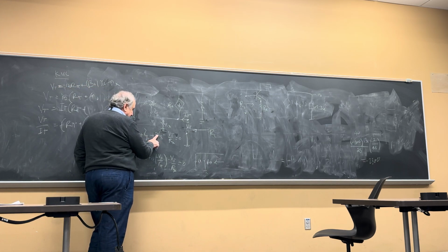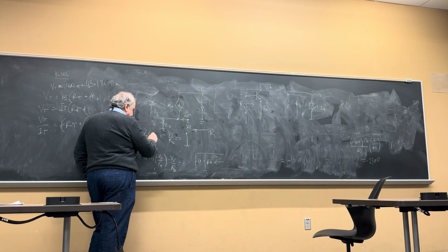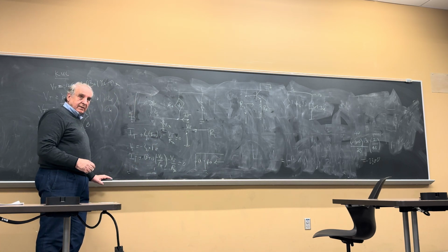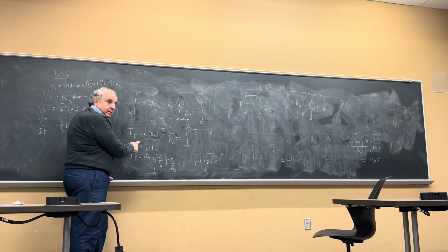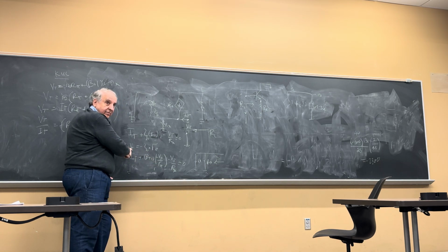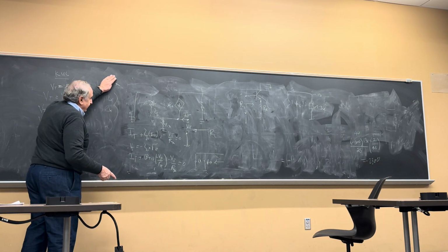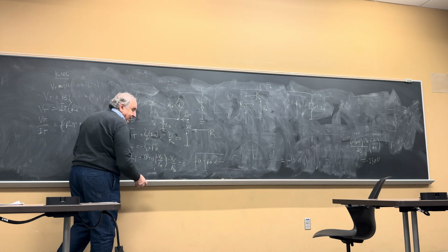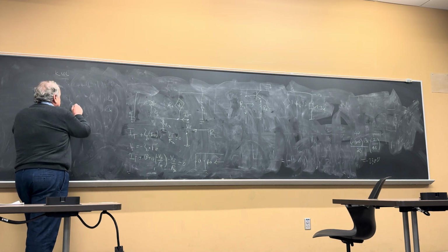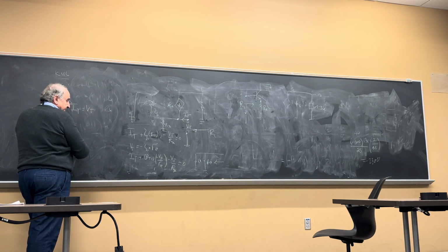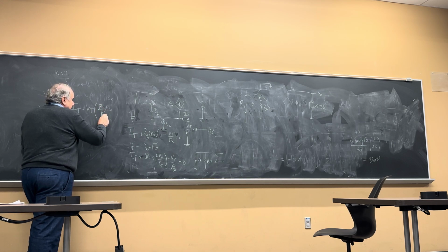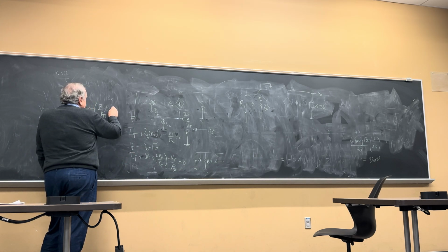Okay, you can write this one as beta plus 1 IB, right? Now I'm going to substitute for IB. What's IB equal to? Vt over R pi, right? They better be the same sign or we're in trouble, because impedance cannot be something minus something. But you can see they're both minus. So you're going to have IT equal to Vt times 1 over R pi over beta plus 1, plus 1 over Rx.